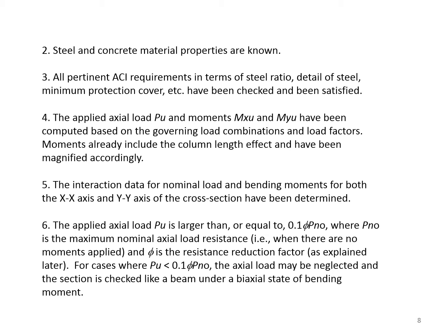Steel and concrete material properties are known. All pertinent ACI requirements in terms of steel ratio, detail of steel, minimum protection cover, etc. have been checked and been satisfied. The applied axial load P sub u and moments Mxu and Myu have been computed based on the governing load combinations and load factors. Moments already include the column length effect and have been magnified accordingly.